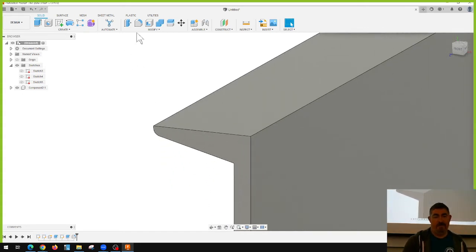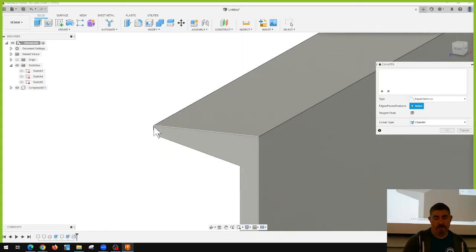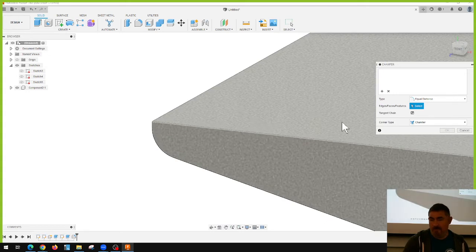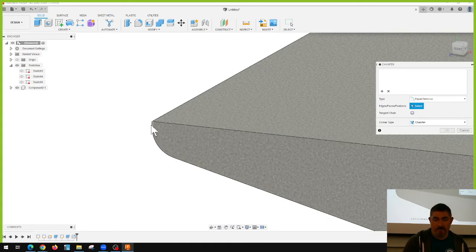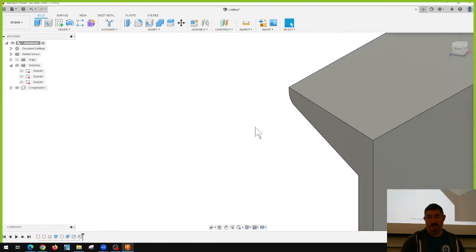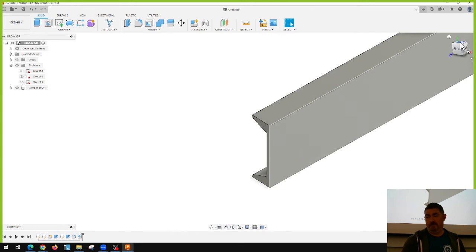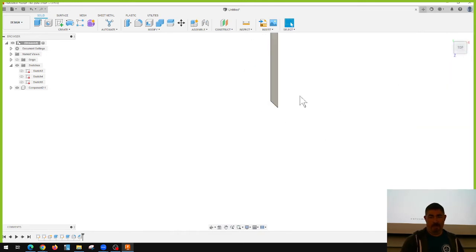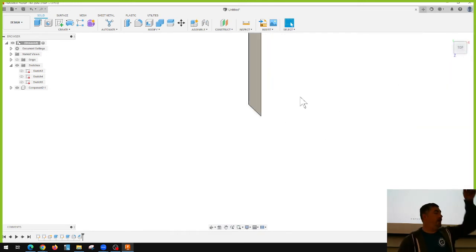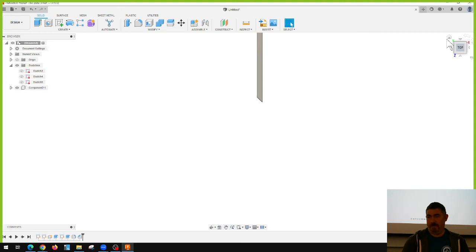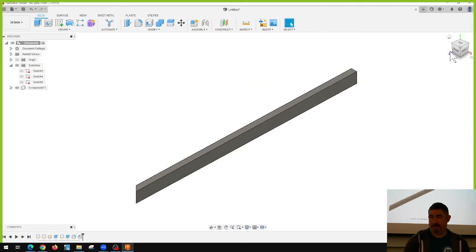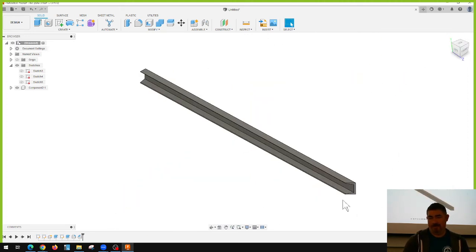So let's see. I do chamfer. If I grab that little bit of a turn off tangent chain, grab right there, and it does do it. So by leaving that little bit of a flat, I can go in and just do a chamfer there and have it chamfered. If my fillet went all the way up and didn't leave that little flat, then I couldn't do that. But if I do this, and I chamfer that first, what happens if I extrude this?